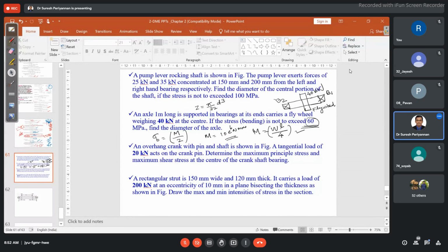Can you do that? We have to verify our shaft diameter. While transmitting the power, the shaft deflection should not exceed 0.36 mm. Then verify whether our shaft diameter is right or wrong. You already know the deflection formula is WL cube divided by 48 EI.